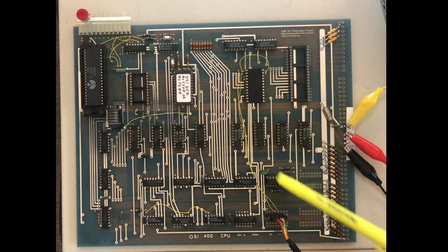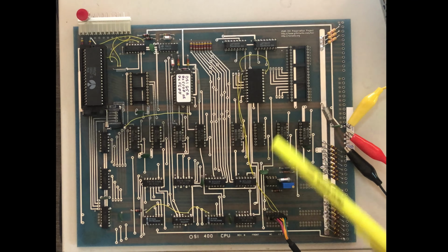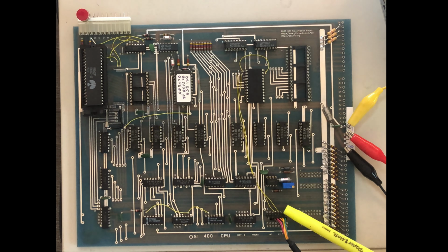The transmit and receive are simply brought over here to a pin header. I've got ground, transmit, receive hooked up here, and this is just a simple RS-232 USB adapter for a PC that has TTL I/O. So I'm not doing any kind of level translation here. It's just TTL level RS-232 connected to Tera Term on a Win 10 PC.